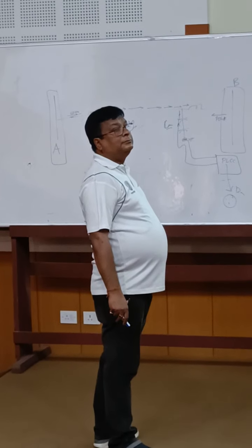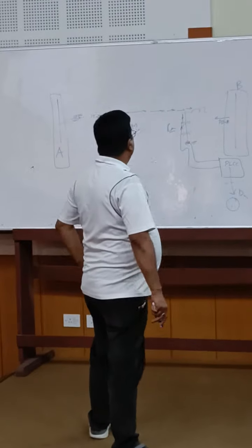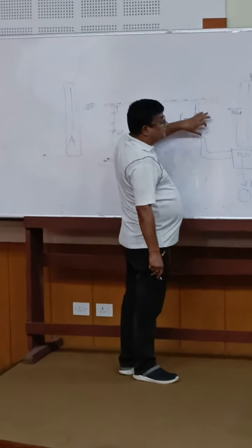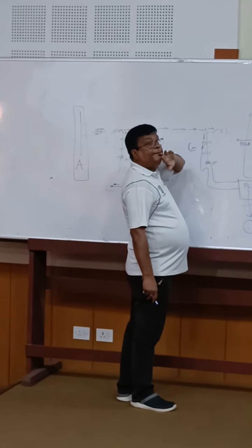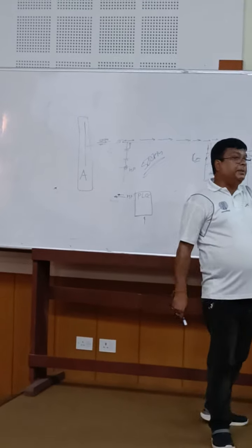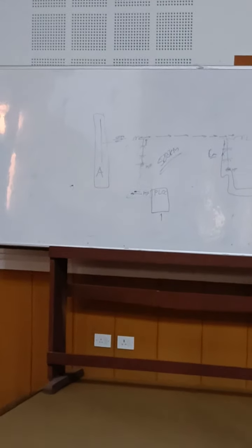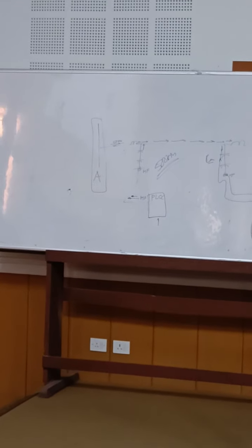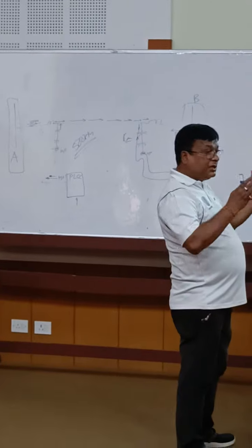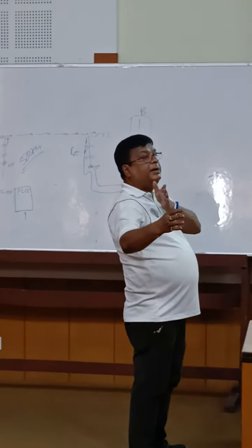In the wave trap, both the inductor and the capacitor are there. Here it will get two parts: one is the inductor and the other the capacitor. So in the wave trap, both the inductor and capacitor are in parallel. But that capacitor is a tuning capacitor. That tuning will tune the particular band there. That is not the blocking capacitor. We have L and C tuning. So the particular band of signal, the communication signal, we will allow, and the other bands will be blocked.